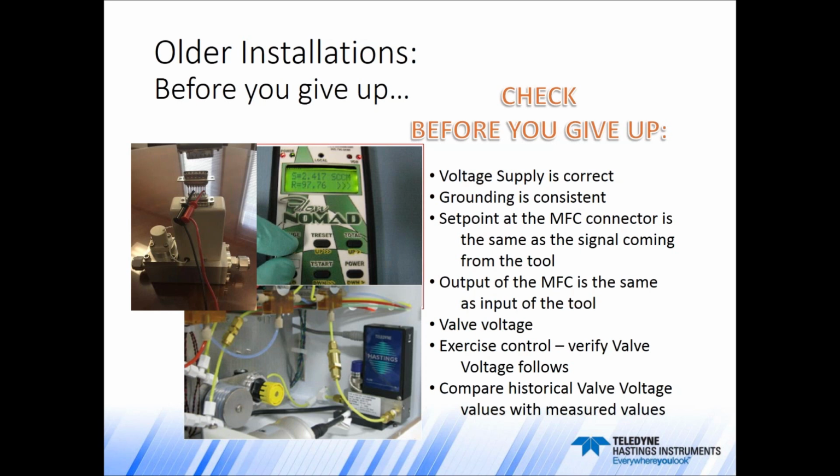Keep in mind that usually the minus 15 channel is the one that fails. This is the one that delivers power directly to the valve operation of most types of flow controllers. So there is a chance that the plus 15 power channel will be okay, but the minus 15 will be faulty. If you get, for instance, minus 11 volts on that particular channel, the power is out of spec. So that's one of the things that should point you in the right direction.